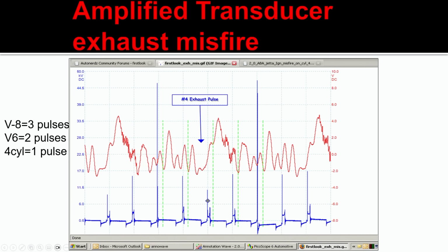I get a scenario, the customer says it's running rough. Whether or not there's a misfire code, I don't care. I could quickly verify if it is actually running rough, because if it is running rough, it's going to affect the exhaust pulses coming out of the tailpipe, right? Now, if it's a dead misfire, it's going to extremely affect them. So this is something I did real quick. I just walked to the back of the car, and I'm going to do it on camera here in a little bit. I put a pressure transducer in the tailpipe. I get a good go or no-go style test. What I'm looking for is uniformity on these initial tests when I'm using a pressure transducer.